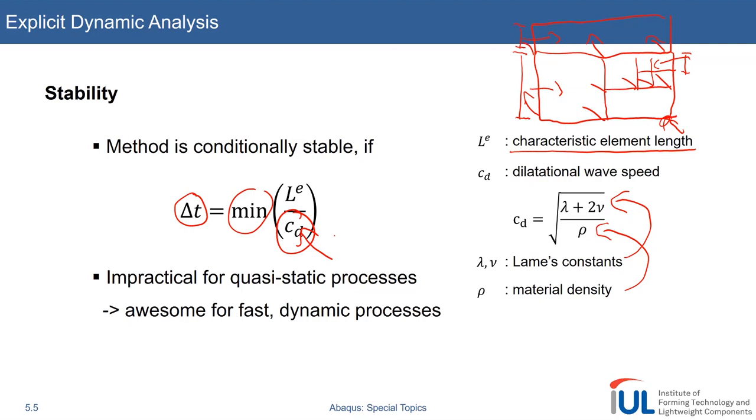If a tensile test is performed at normal speed, you would argue that, except for whatever cracking occurs or the rupture of the entire specimen, this is a quasi-static process. So you'd say, if I need millions of increments, there is no need to simulate this using explicit dynamic analysis. Also, this is just logical, because there's nothing dynamic happening in a simple tensile test, right?